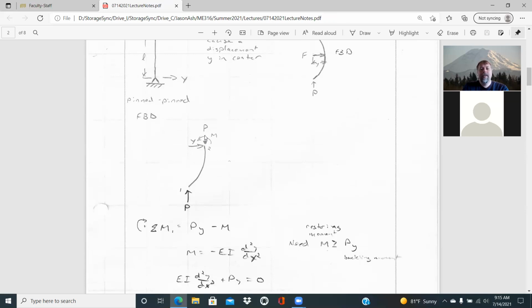You would have the same axial load acting downward. You can verify that just by summing forces in the Y equal to 0. Those are going to be the same. But the other thing that you note is that it causes a moment couple. That would create a clockwise moment about this bottom point. And so then you would need an opposing internal moment at that cut to counteract that. So that's going to be a counterclockwise moment.